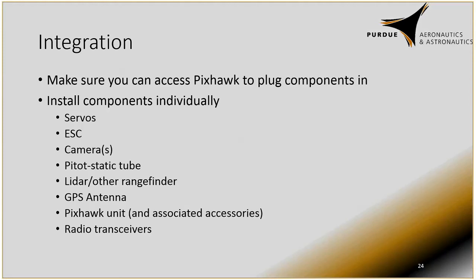A big one in integration, making sure you can access the PIXLOC. If you are putting components in individually, make sure you can then access them after you have put them in. Make sure you can plug your servos in. Make sure your ESC can reach your motor. Make sure your pitot-static pneumatic tubes are long enough. Just everything along those lines.